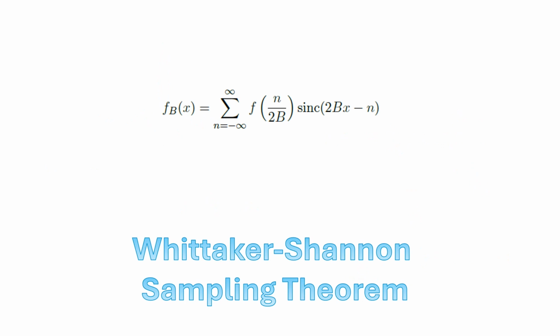It tells us that if we sample the function at these discrete points, we can represent the function exactly. Now, there's a requirement on the sampling rate that the sampling period has to be less than 1 over 2b, where b would be the actual bandwidth of the function. This came up in our definition of the bandwidth that also determined the sampling rate that we have to get. Basically, we set our samples at delta x equal to 1 over 2b. If we undersample, we will get aliasing effects, as we'll see later on in today's discussion.